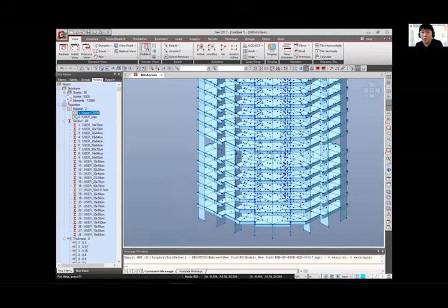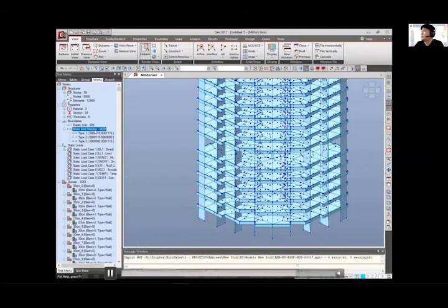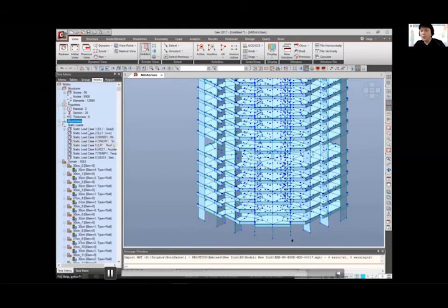And we also have this information about thickness of slabs and walls. And we have some boundary conditions, some elastic links, and some beam end releases, which were also defined in Revit. And let's see, we have the loads. In this case, we have just applied dead load, live load, and wind load directly in Midas Gen. So let's go back to the presentation.